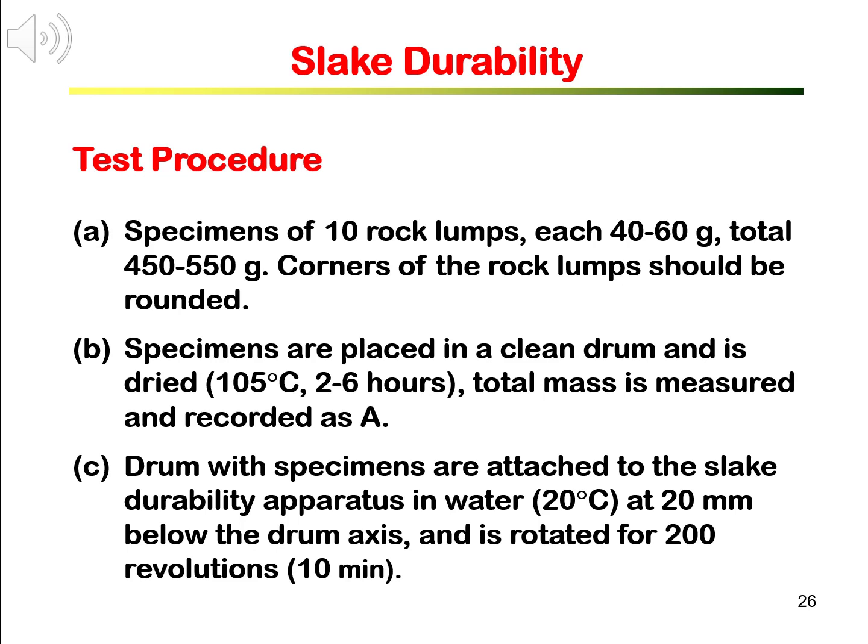Switch on the motor and rotate the drum and let the drum rotate for 200 revolutions or 10 minutes. Remember, the rotational speed is 20 per minute.